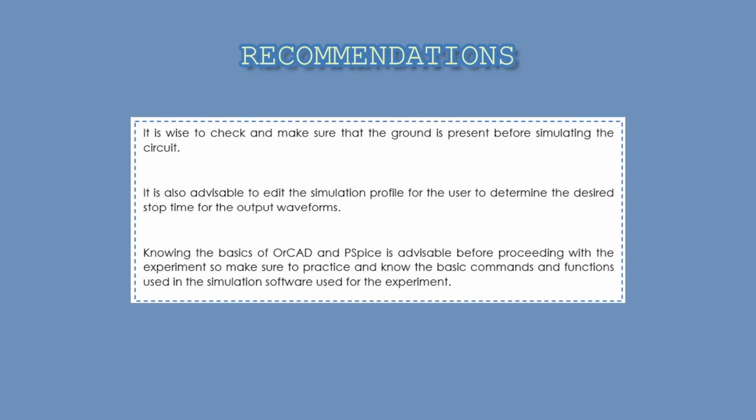Recommendations: it is wise to check and make sure that the ground is present before simulating the circuit. It is also advisable to edit the simulation profile for the user to determine the desired stop time for the output waveform. Knowing the basics of OrCAD and PSpice is advisable before proceeding with the experiment, so make sure to practice and know the basic commands and functions used in the simulation software used for the experiment.